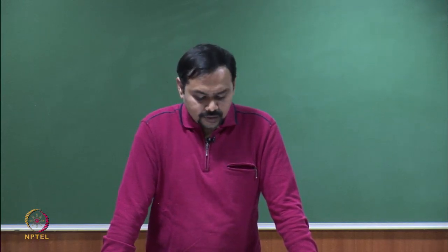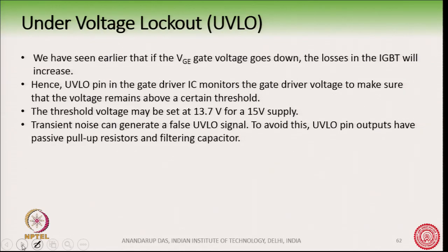Okay. But remember there may be a transient noise sometimes for a false UVLO signal. So, generally these UVLO pin outputs have passive pull up resistors and filtering capacitors, okay, to get rid of the transient noise and a false UVLO signal.